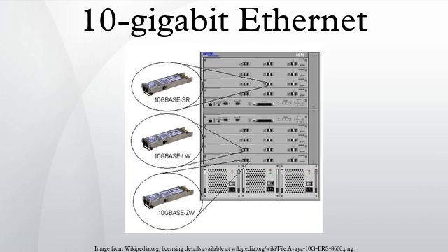10GBASE-T, or IEEE 802.3an-2006, is a standard released in 2006 to provide 10 Gbit/s connections over unshielded or shielded twisted pair cables, over distances up to 100 meters. Category 6A is required to reach the full distance of 100 meters and Category 6 may reach a distance of 55 meters depending on the quality of installation, determined only after retesting to 500 MHz.